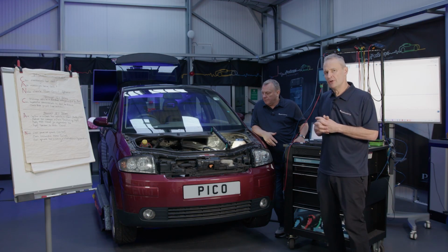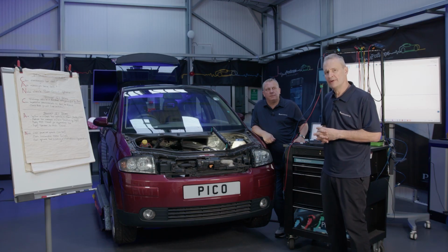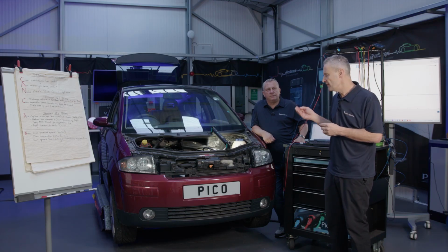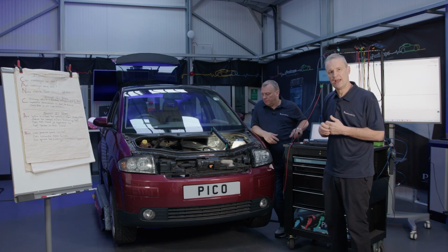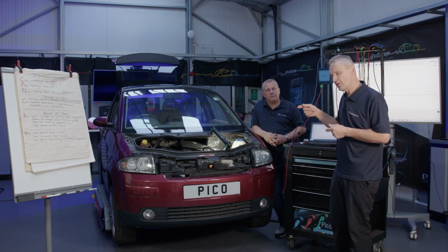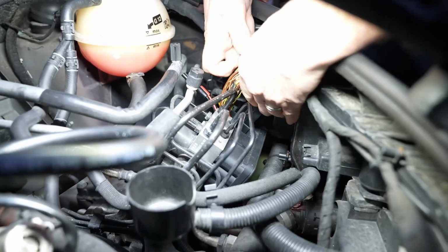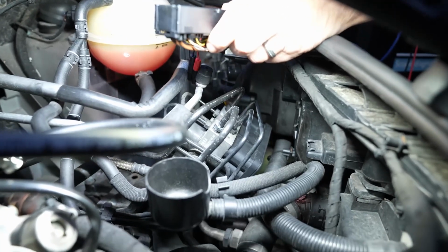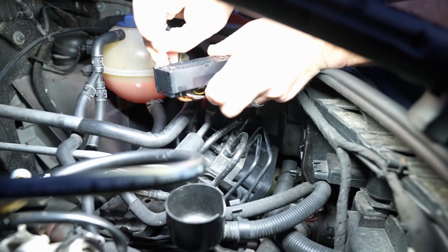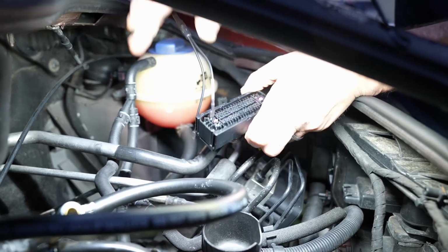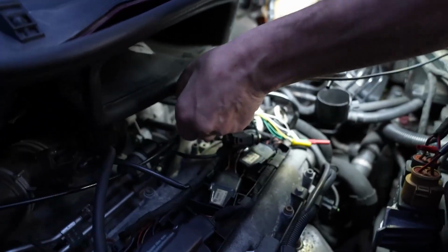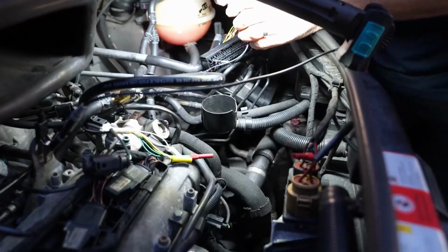Okay, so this is an opportunity also while the vehicle is shut down to have a look at the grounding on the ECU. So let's see how this ABS is referenced to ground, whether we've got a resistance there. We know that this is part of what would be a node check, but let's take advantage of where we are. So Ben, if you want to come in here, we're going to disconnect the ABS ECU, and we'll check for ground on this computer. There's a couple of ways we can do this. The first way is we will use our breakout cable, and then we'll use the resistance lead. So we're going to come in, obviously reference to ground, so we're going to connect here.